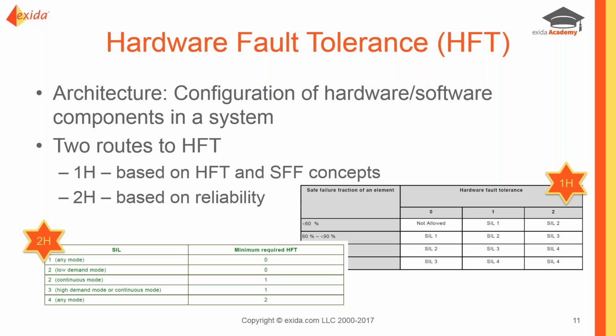So your functional safety management plan needs to look at how you want to define these architectural constraints, which rule set do we want, and make sure that the requirements are well defined in the plan and in the procedures that support the plan, so that anyone who's working on doing your verification knows which to choose.